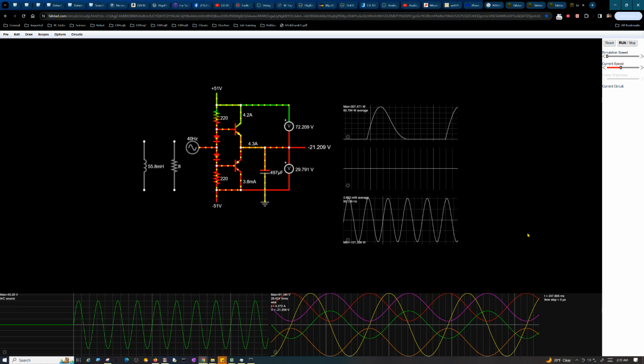A short-circuited capacitor draws maximum current with no charge stored on it. It's an easy-to-remember example: a discharged capacitor, when you first start applying voltage to it, will draw maximum current, especially if you're applying a sine wave. But by the time the capacitor is fully charged, it's drawing zero current, because it's stored all that charge in there, and once the voltage of the capacitor equals the voltage of your power supply, guess what? It doesn't need any more current. So that's why voltage lags current. Current leads voltage in a capacitor. It's just the opposite of an inductor.